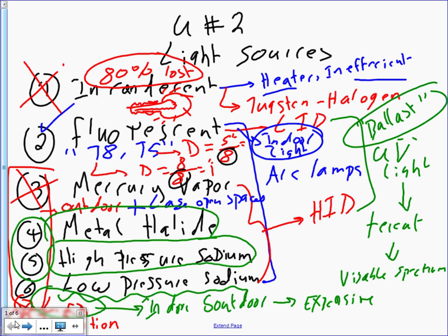As you flip the switch, the current is going to go high, an inrush on the fixture, for 5 seconds. Then the current starts going down, down, down as the output, the lumens, start going up, up, up to reach the 100% value. Okay, for both of them. Anyway, if you want to sit for your certified lighting designer exam, these are a big deal.